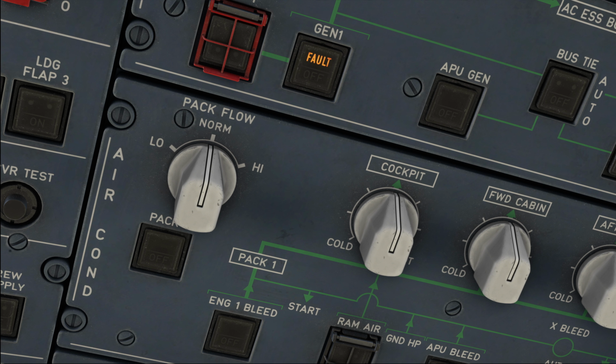Now last but not least, I want to give you a little insight into some numbers used by other airlines for the pack flow, since basically, as I told you, all airlines start to develop their own procedures here. Giving you some examples here, there is one airline that is going to use pack flow low on the A320 with passengers up to 115, and pack flow ECON with up to 140 passengers on the Airbus A321.